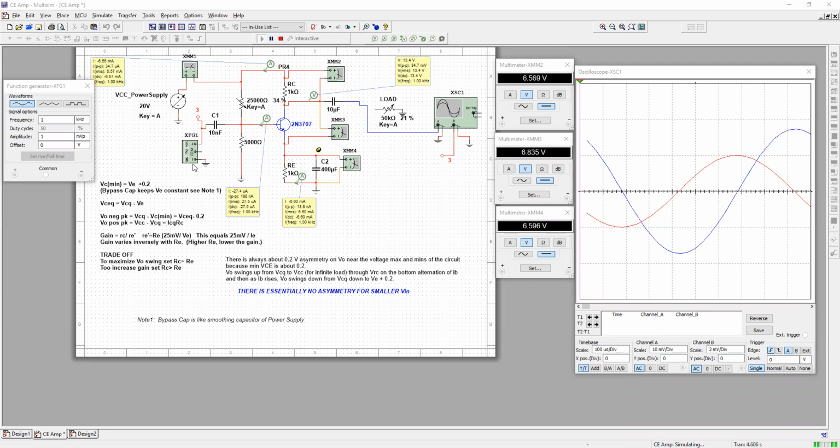In order to understand what's happening here, we have to review the role of our capacitors. Big capacitors will act like a wire. In most cases, the larger your capacitor, the more negligible the effect it has on your circuit. So it will pass everything onto the resistor, whether it's low or high voltage, and it's really not doing much to constrict the operation. They do make great smoothing capacitors, though, when they're in parallel. We'll talk about that more later.